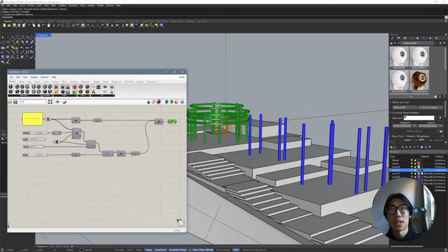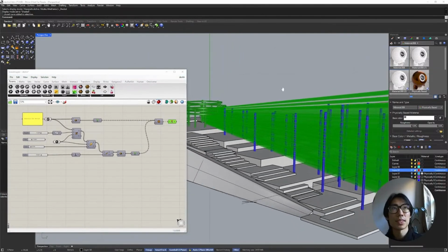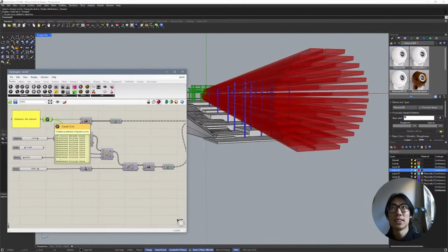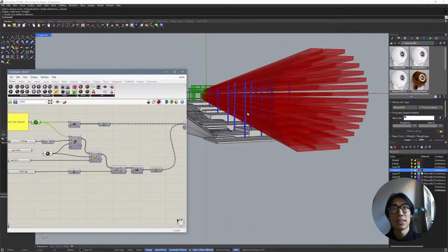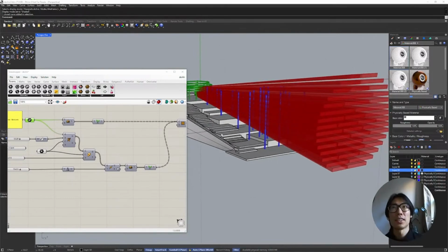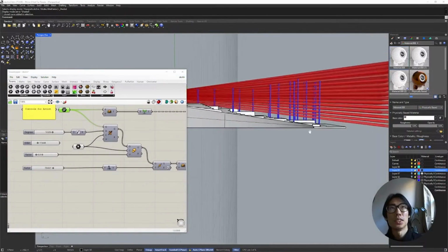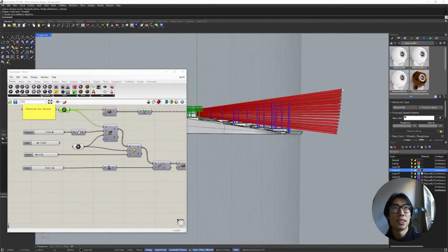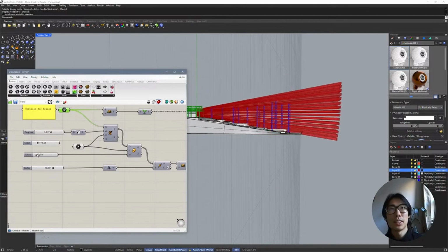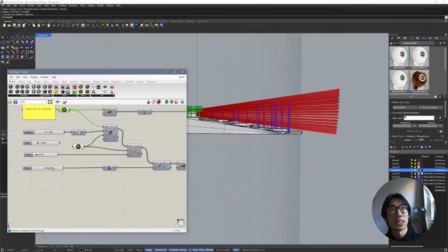I'll turn on what this Grasshopper script looks like. So this is the generated geometry. What this is doing is it's taking that curve data and then it's extruding it along a path so that it connects the smaller rectangles here to these larger ones that are shifted away. And now here the artist has control over the tilt of the final face of all of these. So that's what this little slider does here. And now they can also choose how big the final face is and how far it extends.